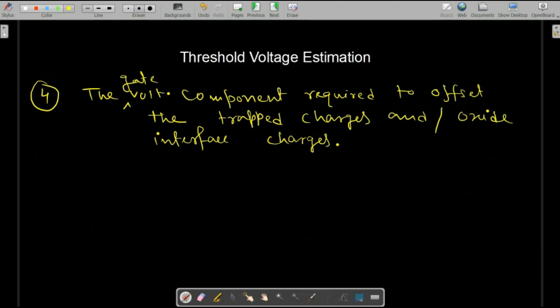So remember that oxide we are going to deposit. Although theoretically we are saying that it is a perfect dielectric, inside every oxide, especially those fabricated during this MOS fabrication technique, there are some impurities, some defects or imperfections. So there are some oxide defects.